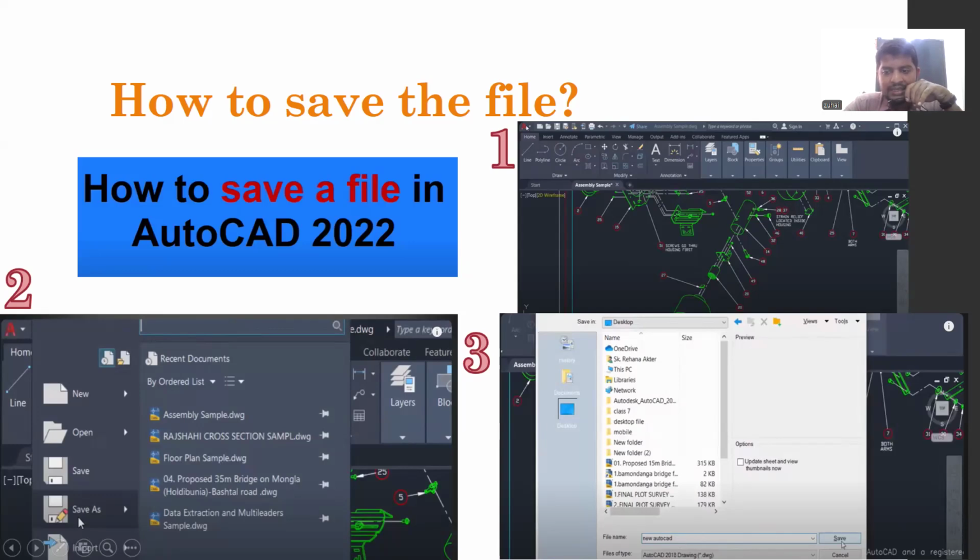And you have to click this other drop down, the file type drop down, and save as a DWG file, drawing. There are several options. You have to click and save that one. Then after that you have to click the Save option finally to save this file. This is the way you are going to save.